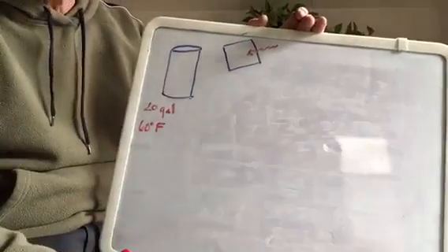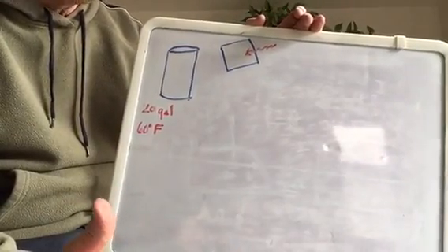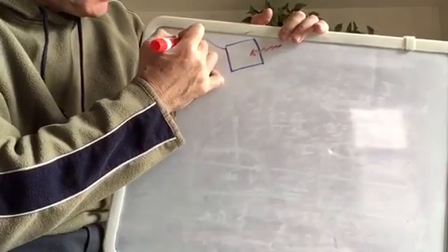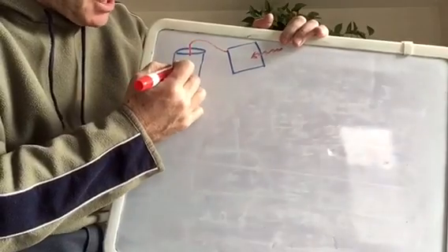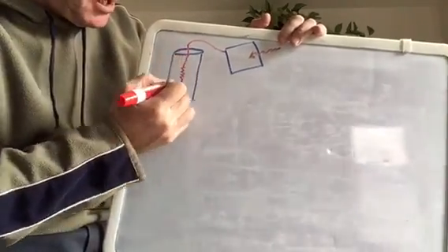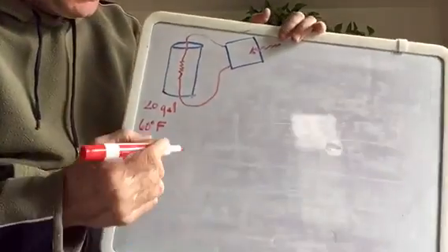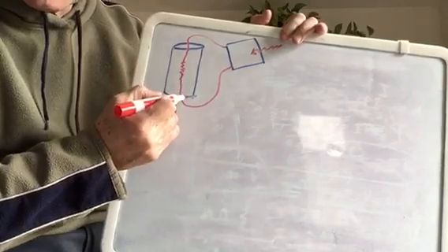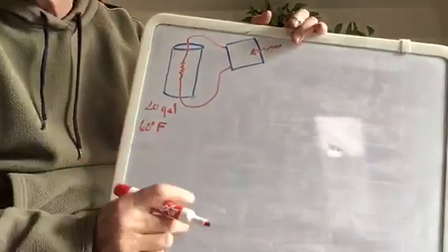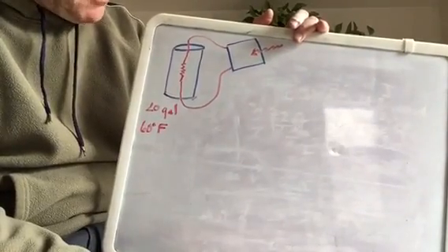Well, one of the beauties of PV compared to solar thermal with hot water is that with solar thermal, you're moving the energy with pipes, whereas with PV, it's just wires. So we would have a wire that comes in and enters the tank, and then we would have some sort of resistor in the tank. It wouldn't be suspended, but I can represent it that way. And then we would have wiring that would go back outside the building and connect to this PV panel. And boom, we're going to get current going through that resistor, and that resistor is going to warm up the water, and it's going to come back, and then the current's just going to keep flowing as long as there's sun. All right, so how would we work that out and try to make sense of it?